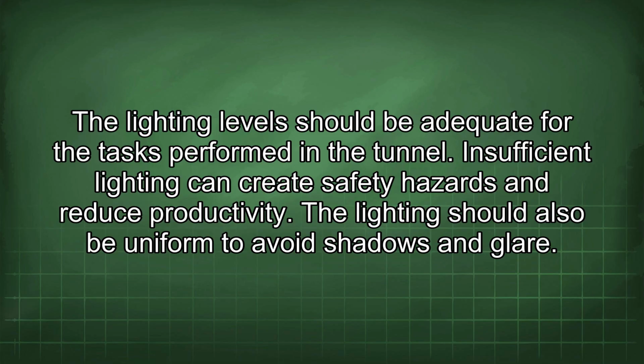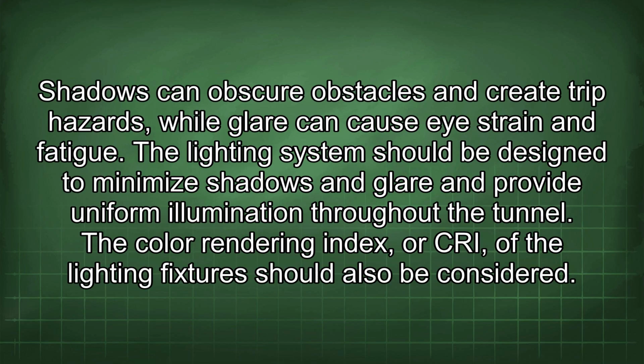The lighting levels should be adequate for the tasks performed in the tunnel. Insufficient lighting can create safety hazards and reduce productivity. The lighting should also be uniform to avoid shadows and glare. Shadows can obscure obstacles and create trip hazards, while glare can cause eye strain and fatigue. The lighting system should be designed to minimize shadows and glare and provide uniform illumination throughout the tunnel.